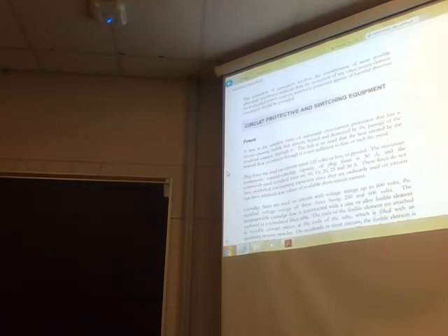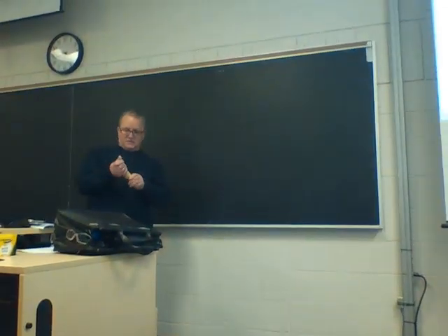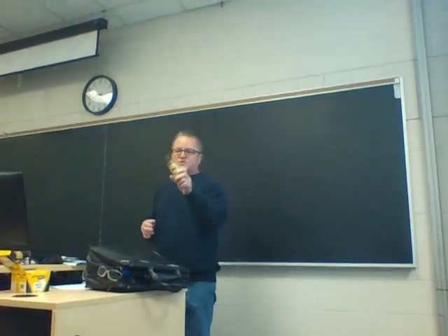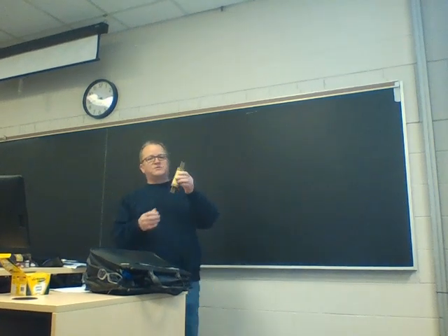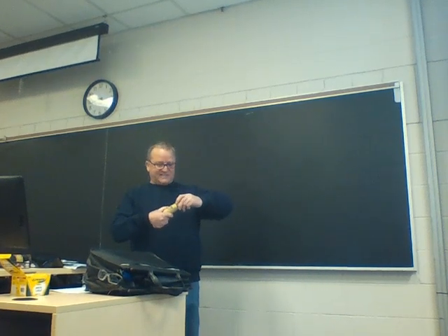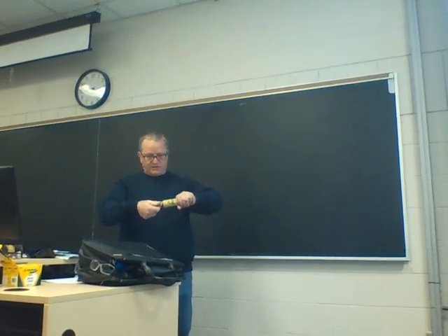A fuse is the simplest form of automatic overcurrent protection that has a circuit opening fusible link directly heated and destroyed by the passage of the overload current through it. The link is so sized that the heat created by the normal flow of current through it is not sufficient to fuse or melt the metal. And I have an older style cartridge fuse that if you take it apart, it has a replaceable fuse link.